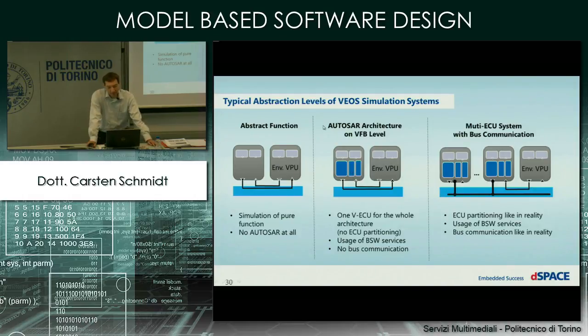And this is the stage where you would typically do a VFB level simulation. So you simulate the AutoSAR architecture, but you don't consider bus communication, but you use the virtual function bus level for the communication of the software components.